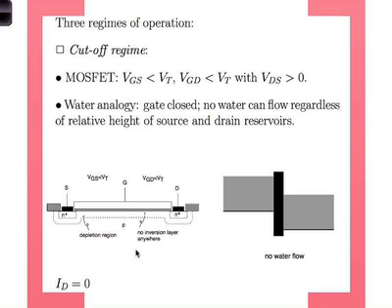From the device perspective, let's see what this means. Okay? In this region, a very small voltage is applied between the gate and the source. So here, nothing really happens. Okay? Basically, it remains as a lightly doped semiconductor, nothing happens. Okay, and you have a very low voltage on the drain to source, but this is reverse. This is a PN junction. Okay, and this is a reverse bias PN junction, right?